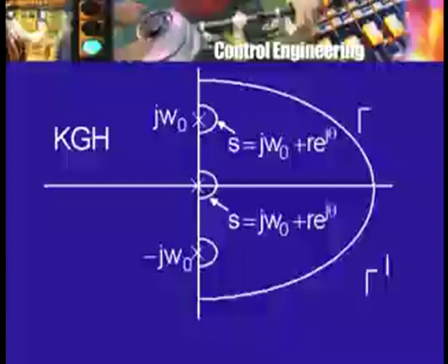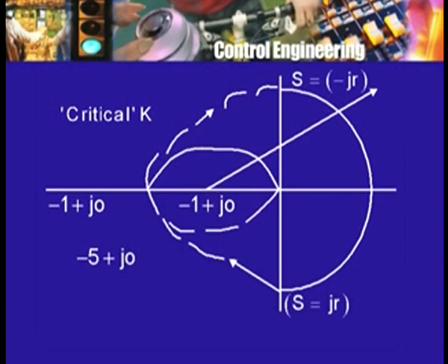The fourth will be, of course, the point of intersection of the image contour gamma prime with the negative real axis, because as we saw in our example, it is that point which turns out to be very critical, as shown here. What is happening here is usually of no concern to the encirclement, because the encirclement is at the point -1 plus j0. What is happening on this side, one has to be very careful. So, one will have to obtain the location of this point.